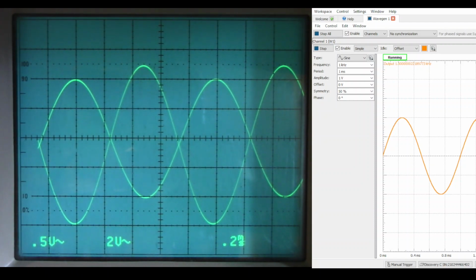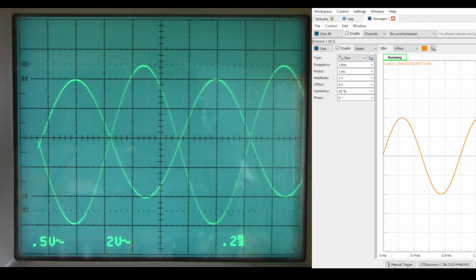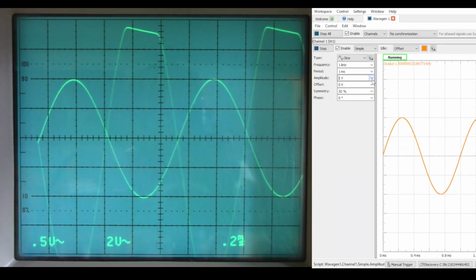Or if you prefer, about 5.5 volts peak, which means that this amplifier has a gain of 5.5, which is what we'd expect when we have an emitter load consisting of two 2.2K resistors in parallel. So that's 1.1K divided by the 200 ohm emitter resistor. So 1.1K divided by 200 gives us a gain of 5.5. If we put the capacitor in bypassing the lower emitter resistor, the gain will increase. You can see it's increased quite a bit, and we actually have clipping.